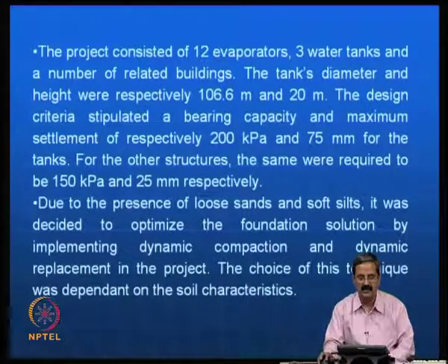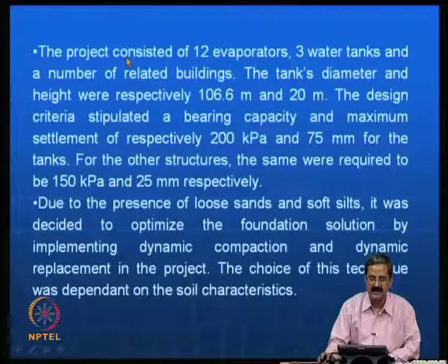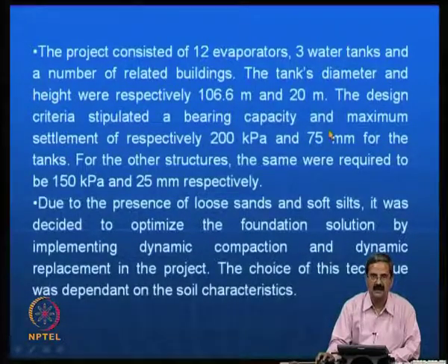The project is quite huge, since it is more of a water supply project. It had 12 evaporators, 3 tanks and a number of related buildings. The tanks' diameter and height were about 106 meters and 20 meters. The design criteria stipulated a bearing capacity of about 200 kPa and a settlement of 75 mm for the tanks.